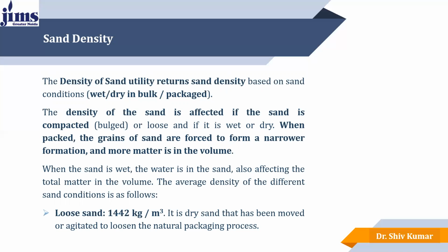It is totally based on the moisture content and the packing. For example, loose sand: the density of loose sand is 1442 kilogram per cubic meter. It is dry sand that has been moved or agitated to lose its natural packing.